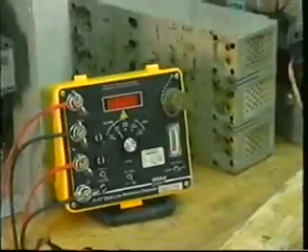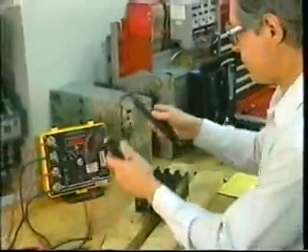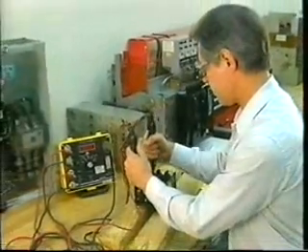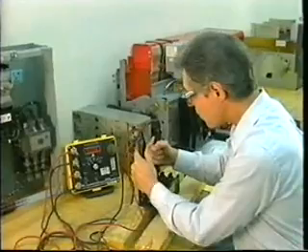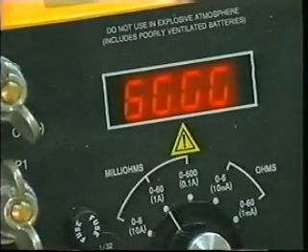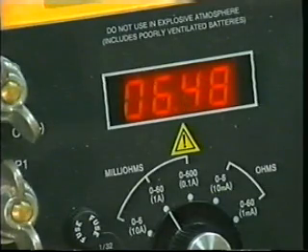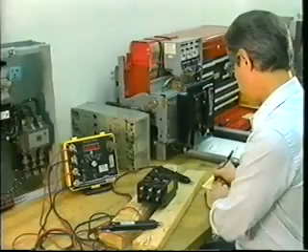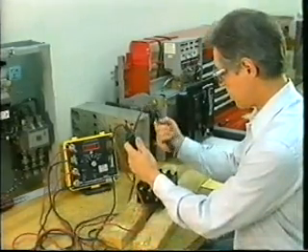The contact resistance test is designed to detect high contact resistance across the breaker pole with the circuit breaker contacts closed. It's usually recommended that this test be made with a direct current equal to the continuous current rating of the circuit breaker. However, currents for the larger circuit breakers may be rated at 100 amps or more. The readings through each phase are measured and compared with the manufacturer's specifications.